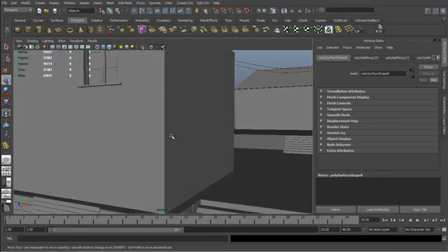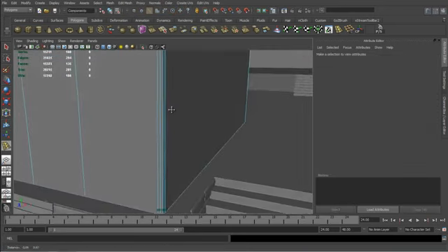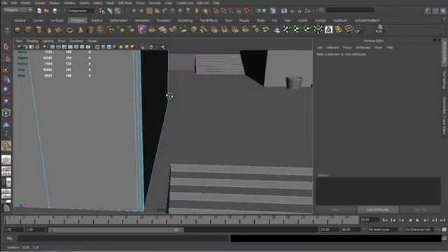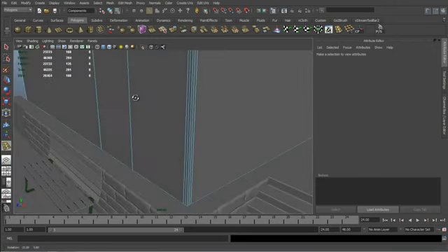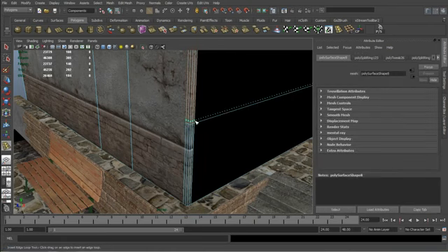That's going to be down there. Again, selecting the edge loop tool, and to view the texture where we're going to place the crack, it's better to turn on the texturing inside the viewport. So now we can add the loops exactly where we want. So the bottom will be here, and the top of the crack will be around there.